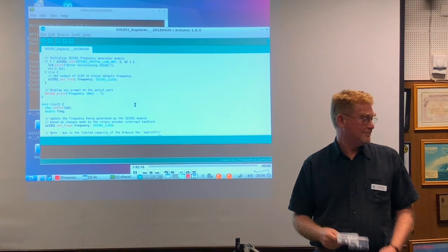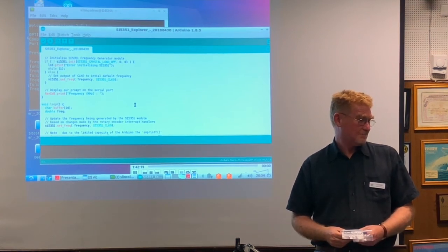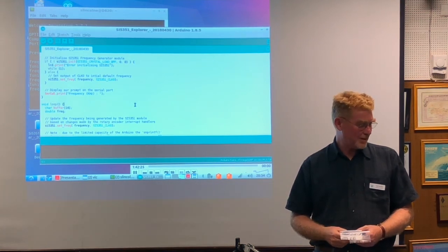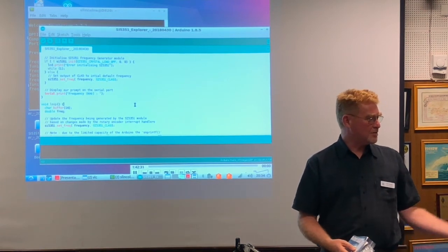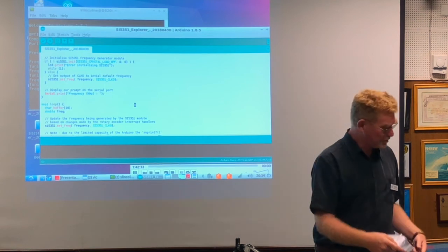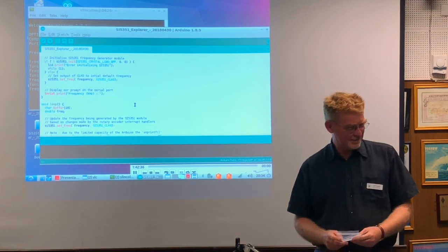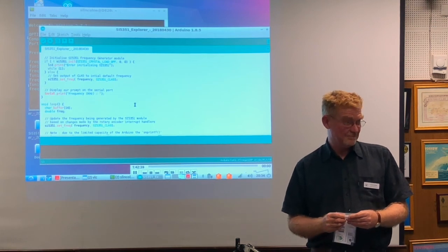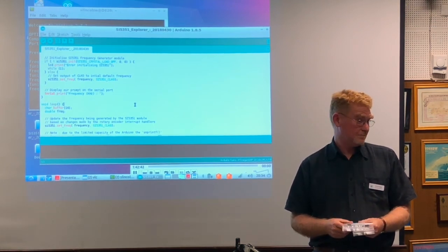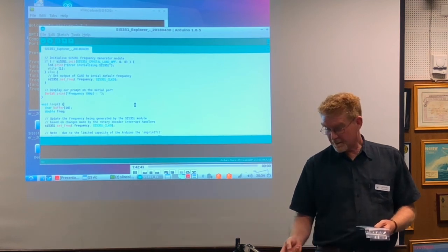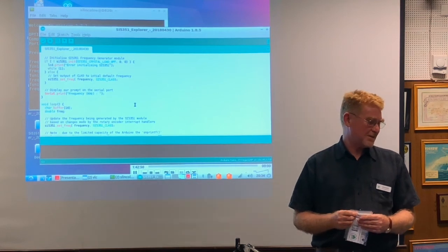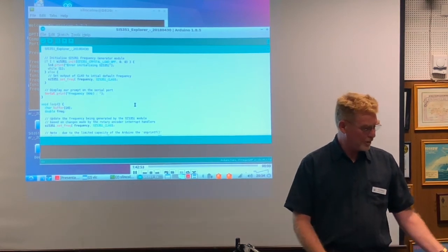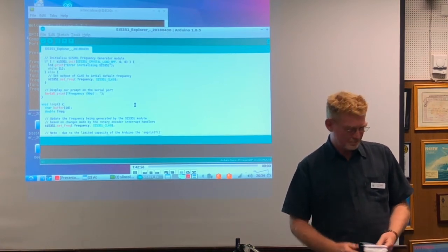So you're connecting to it over the Wi-Fi, so you're not soaking the serial port of that program. Once it's up and running on the air, there's enough smarts in the bootloader to go, oh, this is code, it has banked memory set aside, I'll use that bank of memory for the downloaded program, then I'll flip in and boot off that. So basically you can flip from one to the other, over the air programming. Sorry, I'm not sure I understood that. That ESP module, how do you connect to it and send a new sketch to it? Initially you need to do the connection with your USB port to get code on there. Once you've got the stub on there, you're basically connecting.